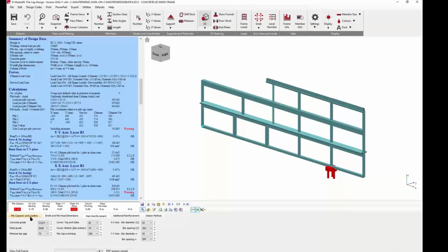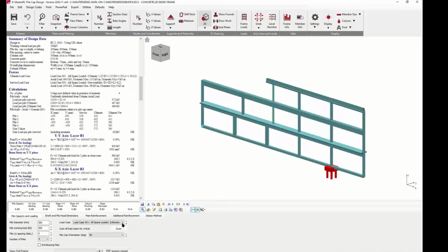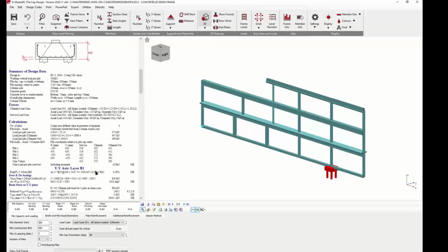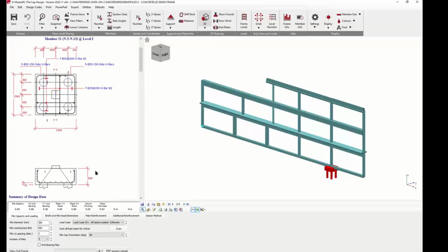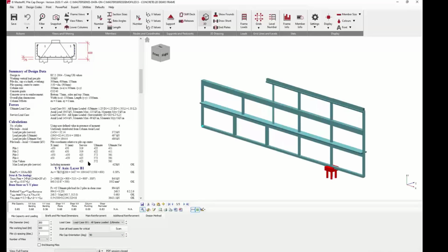So we really need to come back and go into at least a 4-pile cap. And 4 piles are lovely because there's 2 of everything in both directions, and it makes shear a lot better, and bending and everything a lot more simplified.